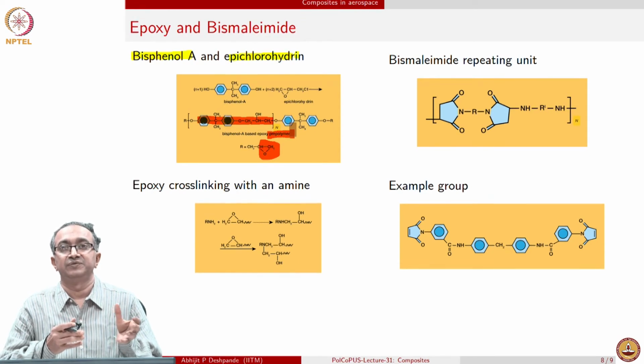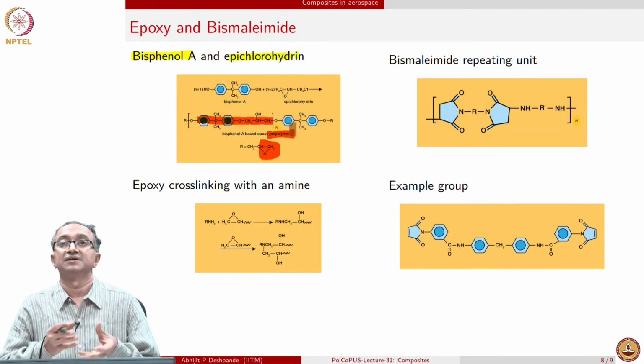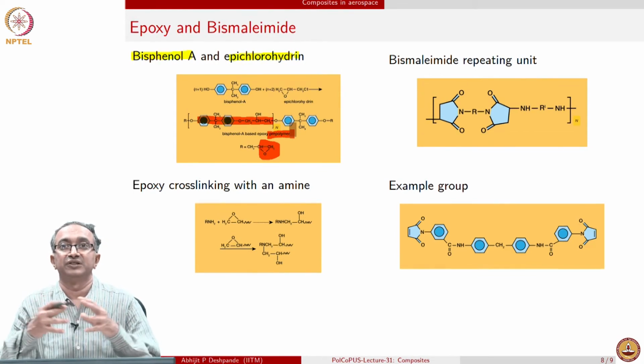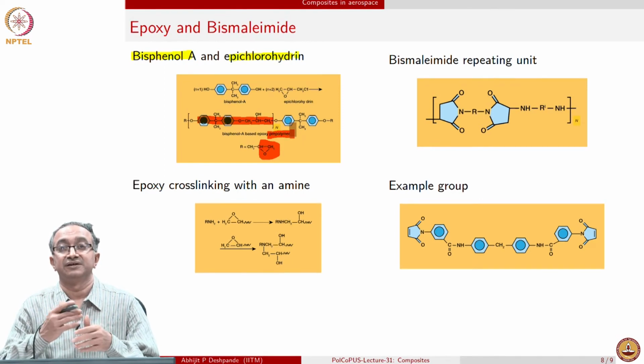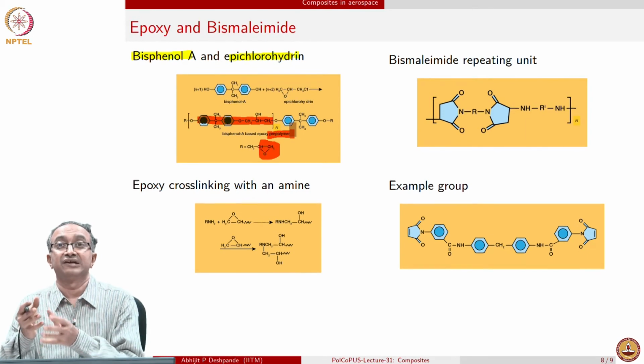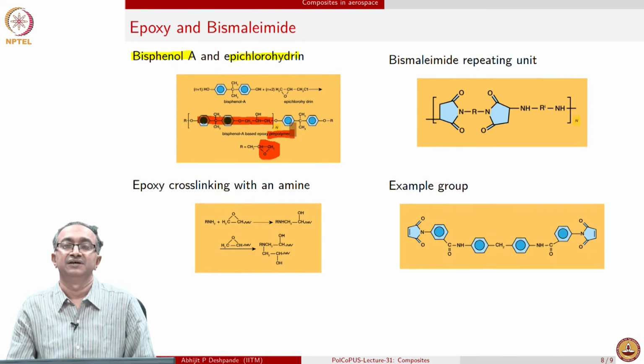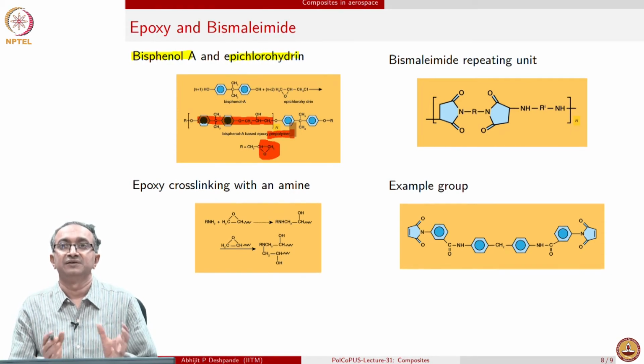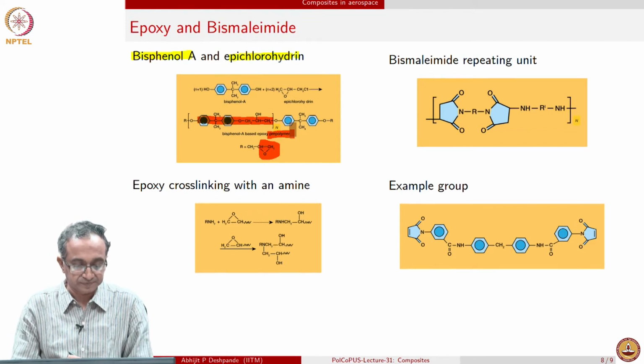Then we carry out the resin flow into the fibrous preforms or fibrous beds or fabrics and so on, where resin has to flow through the porous media made up of all these fibers. Then the pre-polymer is reacted further to obtain the final cross-linked network of the thermoset material. So, there are always two stages of processing in the case of composite materials with thermoset materials.